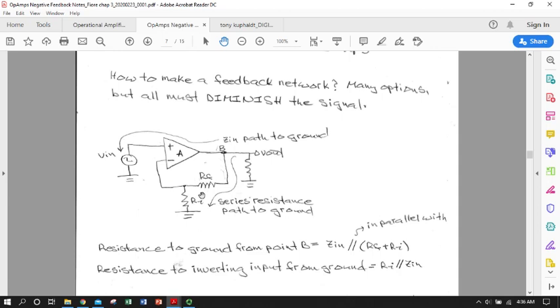And they have those subscripts for a reason, because if you look at the voltage drop over R sub I coming up from ground, whatever current flows through this resistor will raise the voltage at this point by that much, by the voltage drop, and that is the voltage at your inverting terminal, because there's just a wire here, there's nothing else.